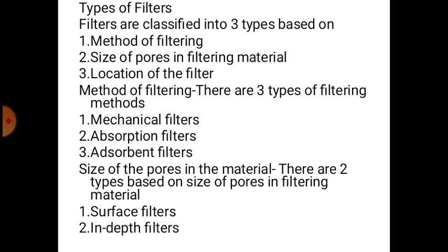Adsorbent filters. Adsorption is a surface phenomenon and refers to the tendency or affinity of the particles to cling to the surface of the filter medium. Filter media include activated clay and chemically treated paper. The capacity of such filters depends on the effective surface area of the filter medium available.